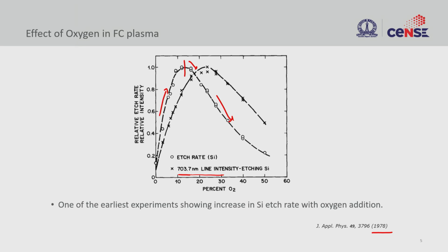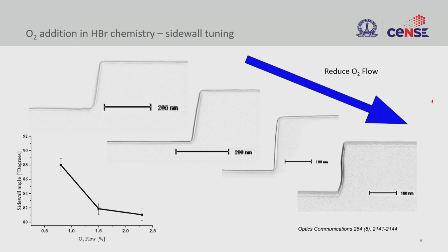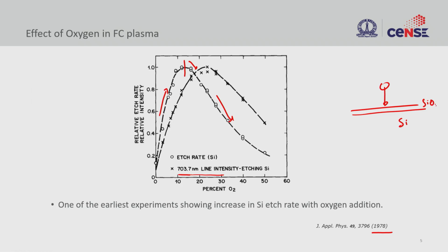So the combination of dilution and formation of oxide on the surface of silicon, right, so you have oxygen radicals that can come in and form a very thin layer of silicon dioxide, which will prevent your fluorine from reaching the silicon. So there is no reaction here, or the reaction rate is very less. So this is how you achieve reduced reaction.